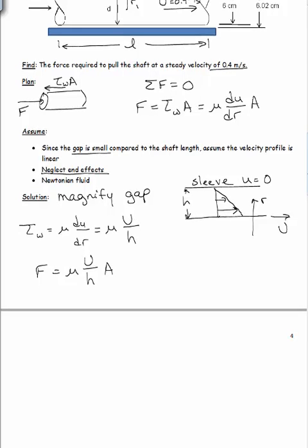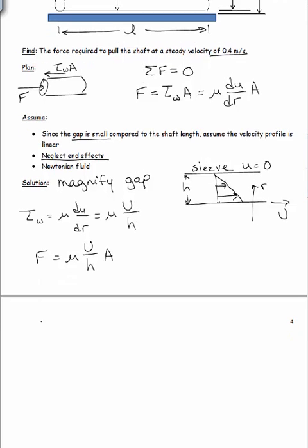So the outside surface is the surface where shear acts. It's not the cross-sectional surface, so it's not pi r squared. It's the circumference times that length. So 2 pi r, so A is 2 pi r1, or pi d would have worked, times L. Okay, that's the surface where the shear stress is acting.